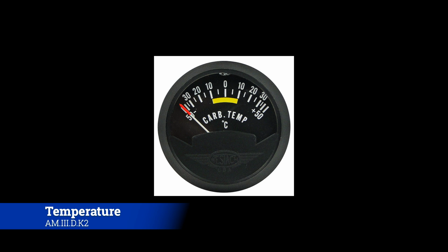Now, as it gets too cold, two things are going to happen. One is that the cold temperatures on the side are going to cause that fuel to condensate on the sidewalls of the Venturi and not be turned into vapor, and it would prevent it from becoming a form that would allow it to combust.